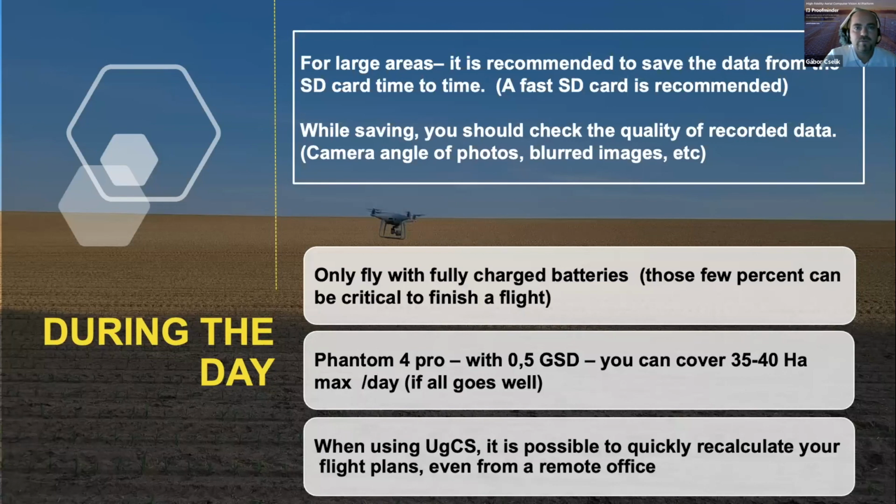During the day when we are working, we suggest you save the data from your SD card from time to time. With the new SD cards, 128 gigabytes or even more, it's easy to forget about it, because you can handle a whole mission without doing any saving, because the capacity of the SD card allows you to do that. But something can happen, you can lose the data, and it's always best to work an hour and then save the data from your SD card.